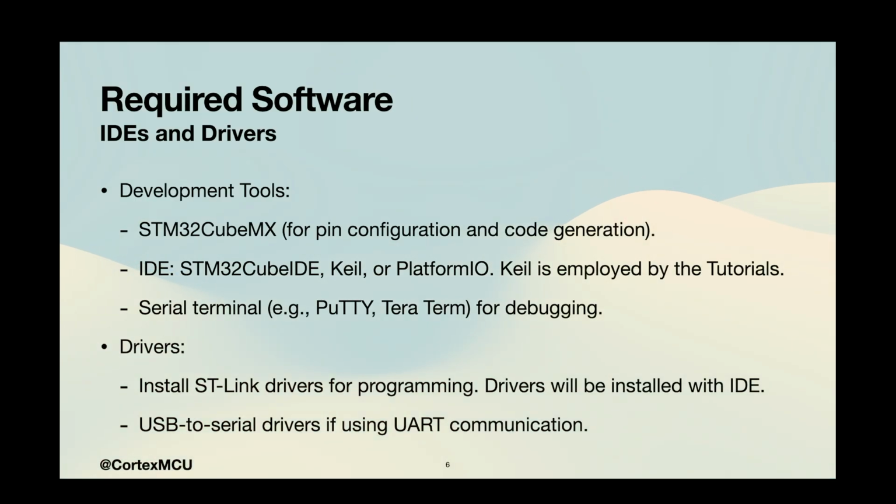And the drivers. Install the ST-Link drivers for programming. By the way, drivers will be installed with the IDE automatically, so you don't need to install the drivers separately. It will be installed together with the IDE. Next one is the USB to serial driver, if you use UART communications.